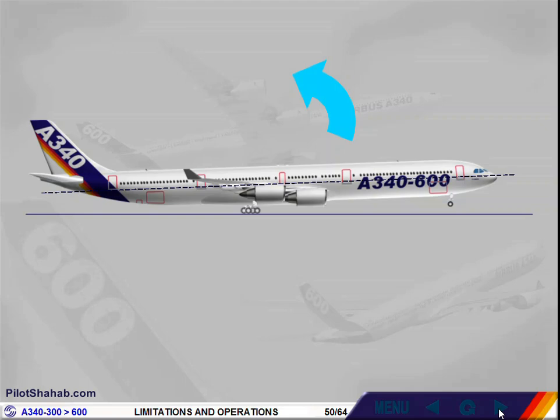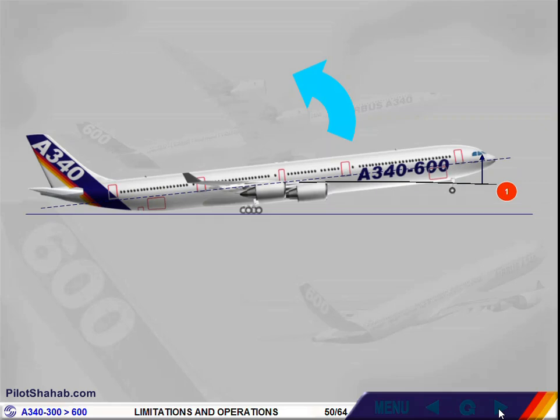First, the pilot senses a delay in the rotation. Then, the local vertical acceleration sensed by the pilot is further increased. This sensory feedback should not lead to overreaction by making large changes to the side stick inputs.